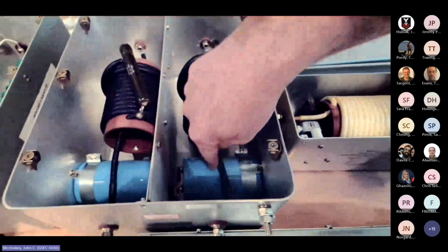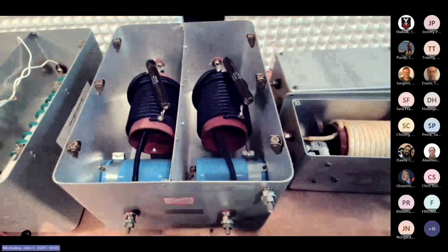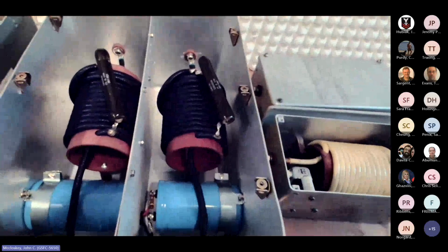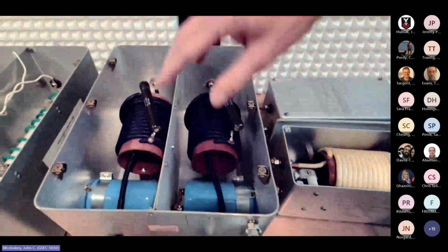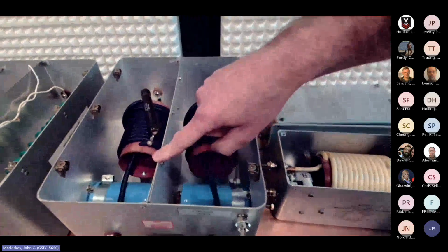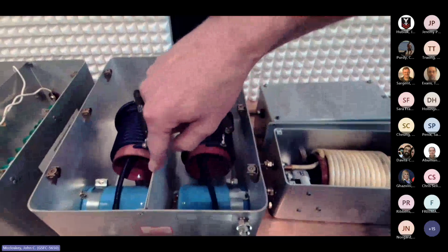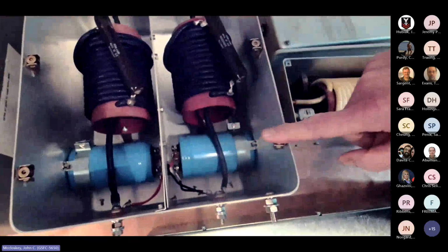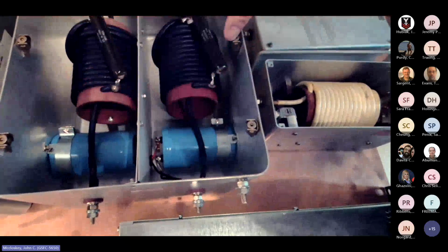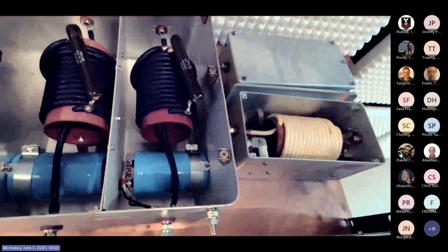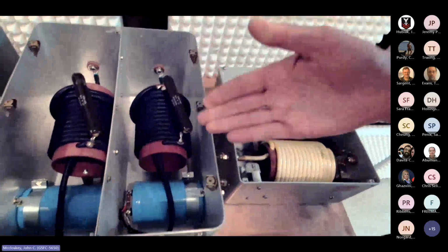There are a couple of big capacitors here on the power supply side. So you feed your power supply leads in this way, and then your EUT would connect to the other side. Here again, you've got to pay attention to the topology. It's not symmetric. Your power supply leads need to go on the side where the capacitors are. If you connect it up in reverse, then your capacitors are shunting out everything before it, and they're not seeing the LISN impedance, and it's defeating the entire purpose. So that's a space station LISN.